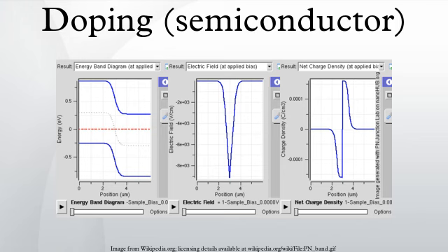of either type. This phenomenon is known as compensation, and occurs at the p-n junction in the vast majority of semiconductor devices. Partial compensation, where donors outnumber acceptors or vice versa, allows device makers to repeatedly reverse the type of a given portion of the material by applying successively higher doses of dopants, so-called counterdoping. Most modern semiconductors are made by successive selective counterdoping steps to create the necessary p and n-type areas.